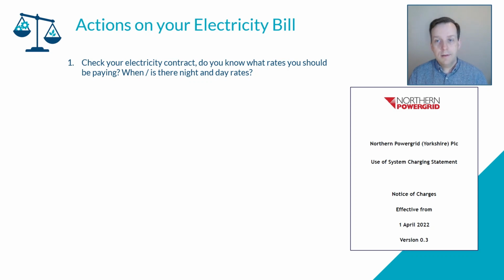So there is a shift that rather than charge businesses for their kilowatt hours at a particular time of day, is to charge them a flat rate for the total capacity they are taking from the grid. And this is why the apparent power is becoming so important and being able to manage it.